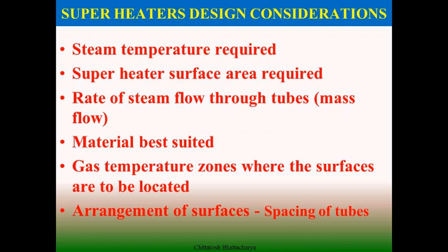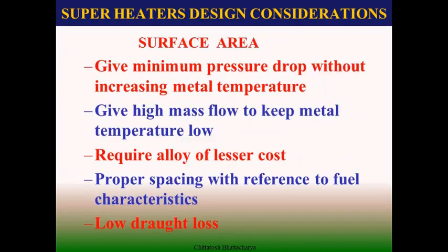So superheating is done very securely, and we try to safeguard the superheating tube elements by staging the superheating in such a way that the tube metal temperature and the steam within the tubing do not have too much temperature difference.